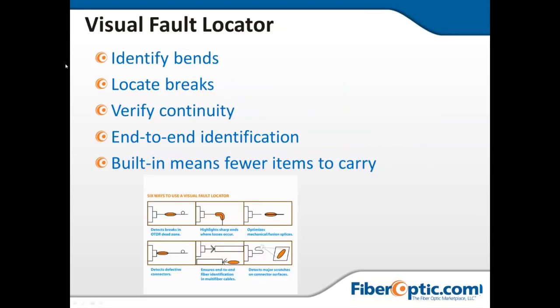It's just turning it on and holding at a consistent power setting, and it doesn't flash at all, so there's no frequency. So it becomes a stable light source at that time. So that works out and allows you to leverage some existing equipment that you have to get an accurate measurement. So very, very possible to integrate a power meter and light source into your OTDR.